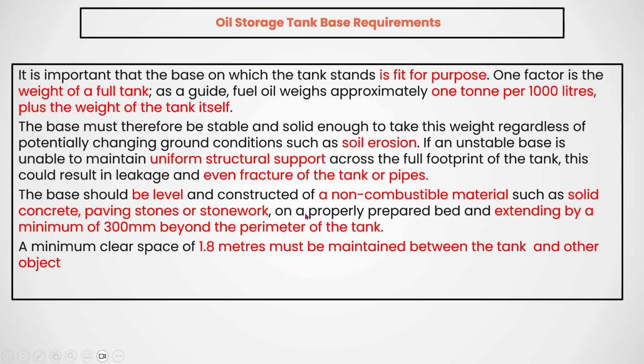Vertically it should be leveled, and the foundation material should be non-combustible material. If some fire takes place in the foundation itself, then a lot of heat will generate, and that will collapse the tank. So it should be made of solid concrete, and paving stones and stonework should be perfect.